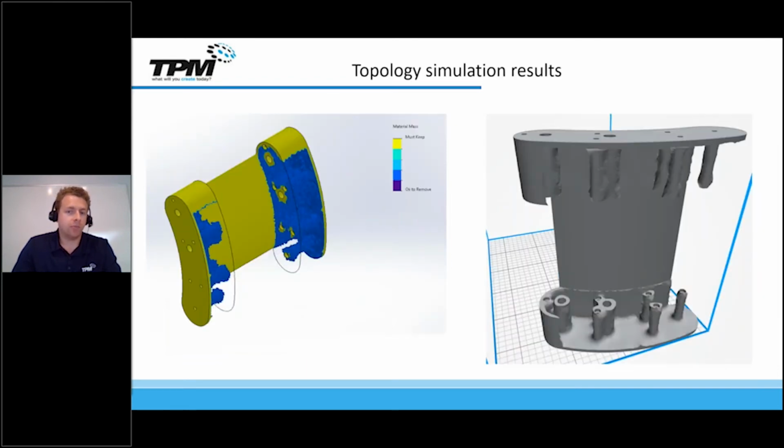So the result of the topology study is pretty interesting actually. The study has presented that essentially all of the geometry that was the meat of the component is okay to remove, and essentially all that is needed is the small 2mm wall thickness we prescribed to maintain the geometry. So this leads us to a dilemma in our design for additive process. We have met the needs of the problem statement, and now we know that this model is 100% printable. In fact, on the right-hand side here, that picture is actually the component straight from the study in the build manager for the HP.